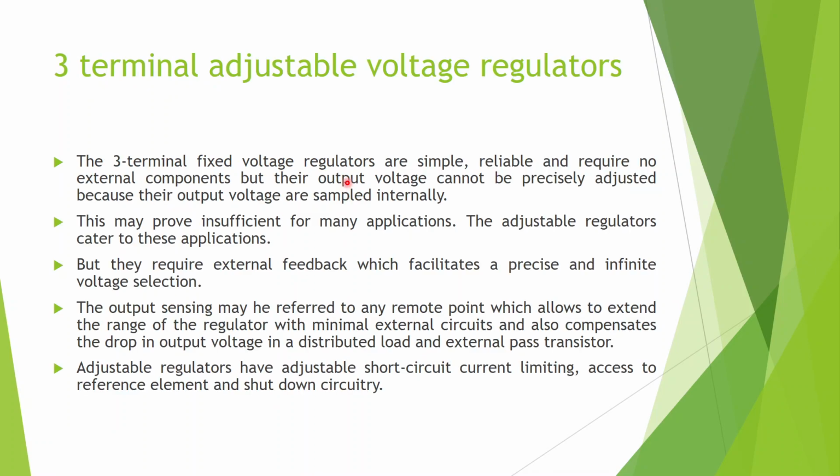Now, till now we have seen 3-terminal fixed voltage regulators. Those regulators have the advantage that they are simple, reliable, and they require no external components, maybe other than the filter capacitors that you add at the input and the output. But they have the defect that the output voltage is fixed. You cannot change it according to your requirement. But you will have applications where you need to change the output voltage. So for such applications you need to have an adjustable voltage regulator.